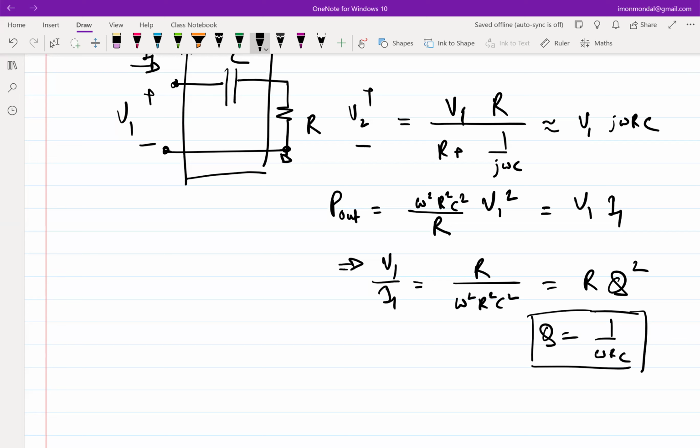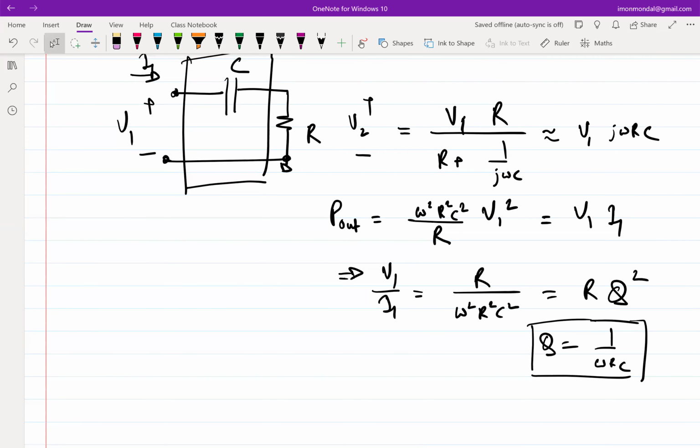So this is obviously when I equate power, I am only concentrating on the real power, right? So this is power dissipated, right? Power dissipated in one port, power entering the other port. I'm not talking about the reactive power, the stored power. That is not a part of this calculation. Fine. So it looks like I have a framework, but this will simply not suffice, because I'll have an imaginary component because of C.